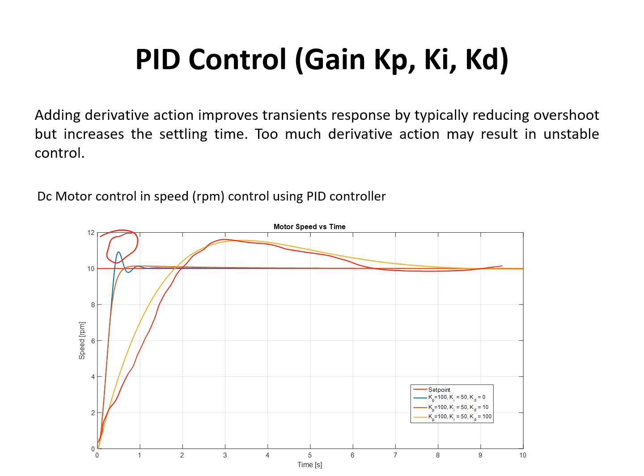So you always start off with a proportional controller and see how it typically responds. You can increase the proportional gain to get a faster responding system until it starts to oscillate, or becomes very overshooty. What you can then do is start adding derivative control, because the derivative control will reduce the oscillations until you get a good responding system.